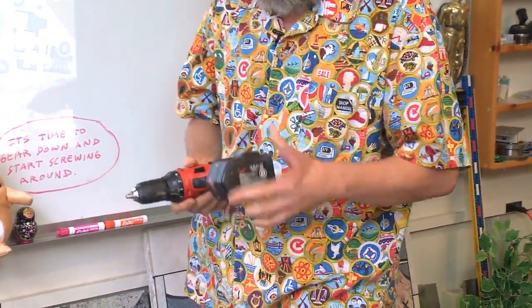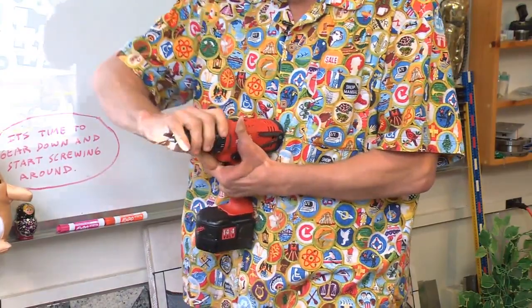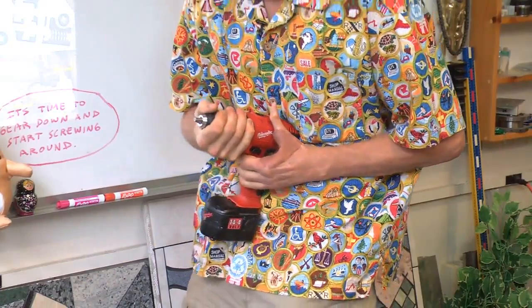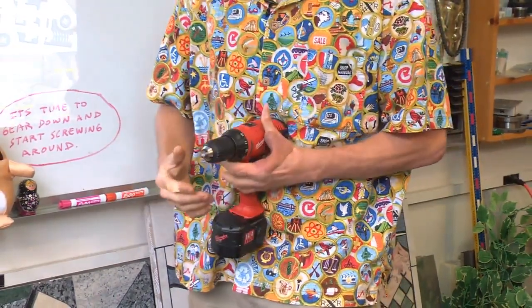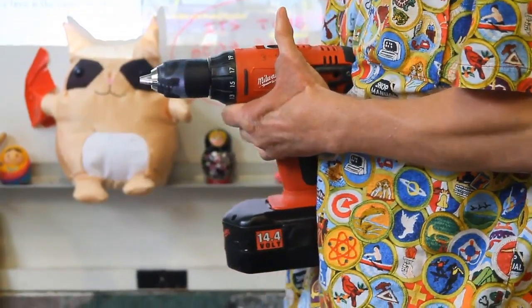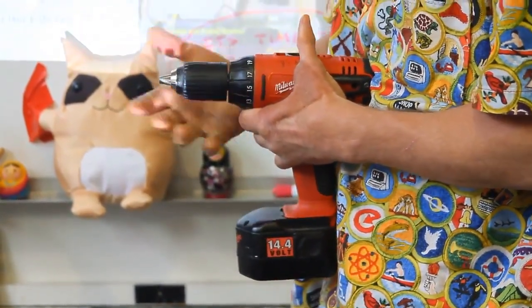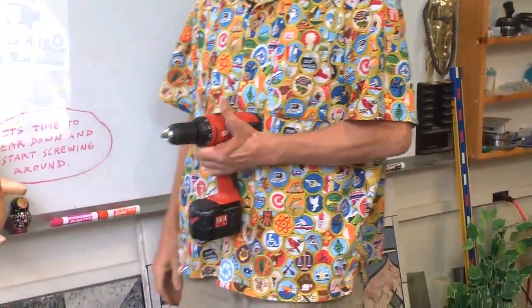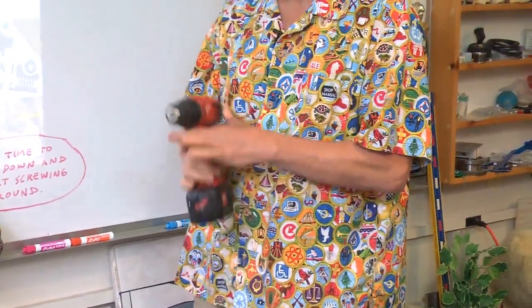Now, in all fairness, this had in it what's called a slip clutch. If you put too much torque, it'll stop. Now we're going to crank it to drill. Let's see if I can do that again. Now, if I put it on high torque, low speed, I can't do it. Much, much more torque. Different function. If you take a little small diameter drill bit and you try to drill with low speed, high torque, you won't drill it nearly as well as when you're on high speed. Now that's into the theory of cutting tools, et cetera.